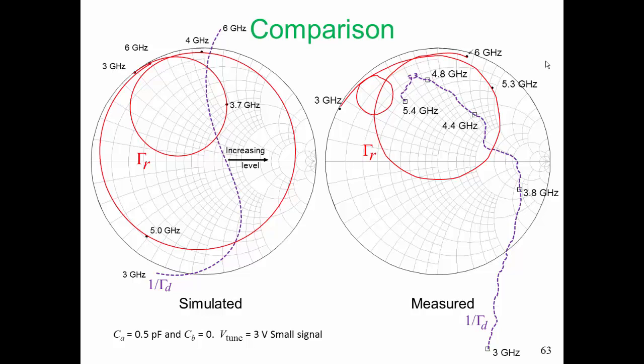Should you believe the simulation, or should you believe the measurement? Well, the truth of the matter is that neither of them are likely to be perfect. The simulated response looks very smooth, doesn't it? It does not show the effect of the many parasitics that we have not been able to incorporate in simulation, such as the sidewall capacitances of components.